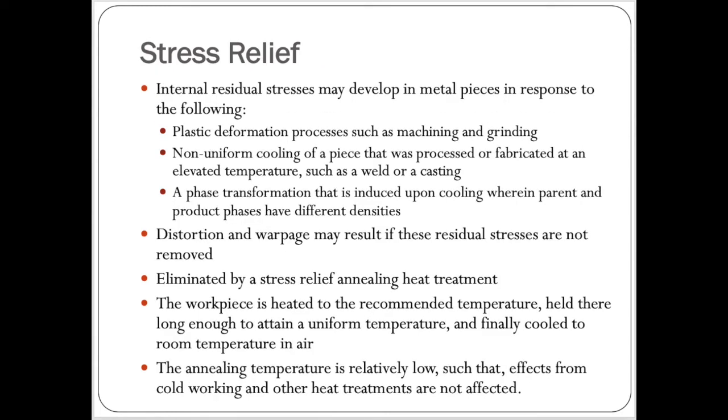The third category of annealing is called stress relief annealing. This stress relief annealing is used when internal residual stresses may develop in metal pieces. These stresses are developed in response to the following conditions. One is the plastic deformation process such as machining or grinding, or non-uniform cooling of a piece that was processed or fabricated at an elevated temperature such as welding or casting, etc., and a phase transformation that is induced upon cooling wherein parent and product phases have different densities.